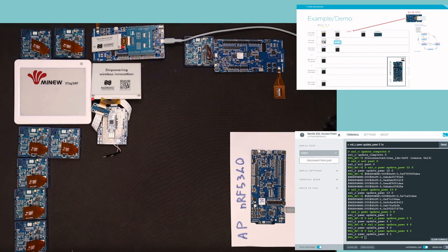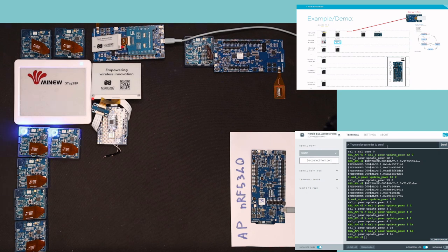Now let's say that we want to turn on the LED in the group number 30. We can do that in this case, and we can then switch off the LED again. So all of this is done over PAwR, and we have seen basically all the steps to associate the new tag and to configure it, to send commands and receive responses, and also to reconnect to the tag while this is synchronized.